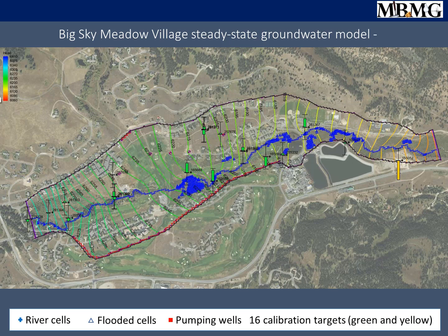And then below the dam here, below the road, there's more flooded cells, but this is a more natural alluvial channel down below, and it's kind of swampy, like I said, there were marshy symbols on the original map. And when we first ran this model, I took the data from the 5 aquifer tests for the municipal wells. And those data gave us hydraulic conductivities. It's a property of how well rock can transmit water. And the values range from about 67 to 151 feet per day.